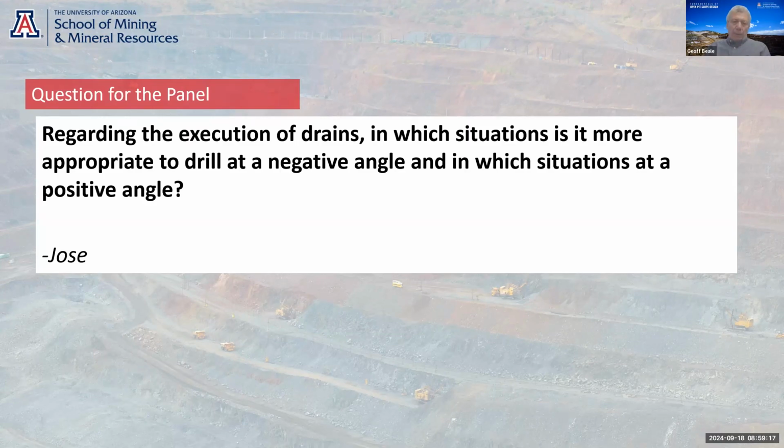So there's less tendency for the water to flow out into the blast damage zone and affect shallow levels of the slope if you drill up. So those are a couple of things to think about, but the bottom line with drains is to think about what you're trying to target. If you're trying to target a structure, think about where it is. If you're trying to target a lithological contact, think about where it is and target the drains accordingly. But within those targets, you've got to think of the things I've just said about the downsides of drilling up and the downsides of drilling down.